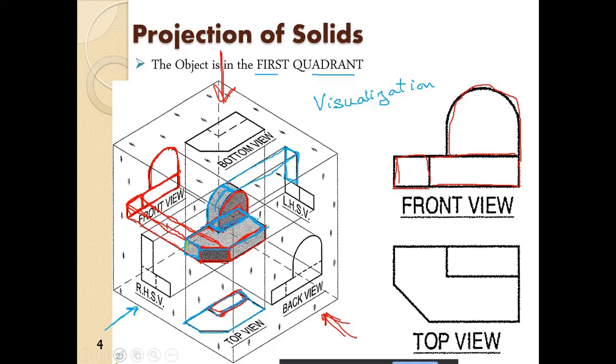So you will see this plane over here, right? So it will be projected on the profile plane in this manner, and again this inclined plane, so it will be projected straight here, this point straight here, right? And what you will see is this section over here. So I hope you could get the idea of what is orthographic projection of solids.